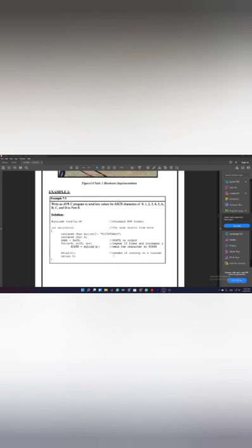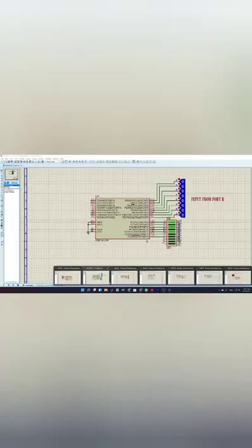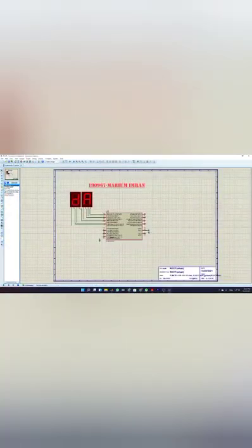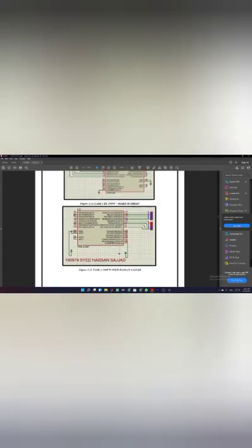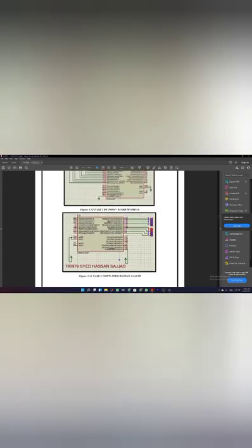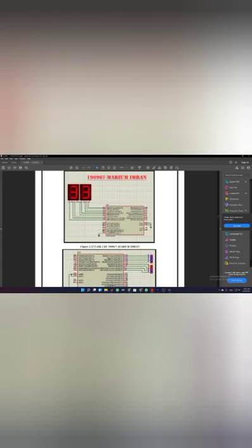the next example, you can see that we have to just write these ASCII characters. We have to send these ASCII values to port B, and we will store all these values into an array, and then after writing it in inverted commas, you can see that it automatically sends ASCII characters or values, binary values, to the port as an output.